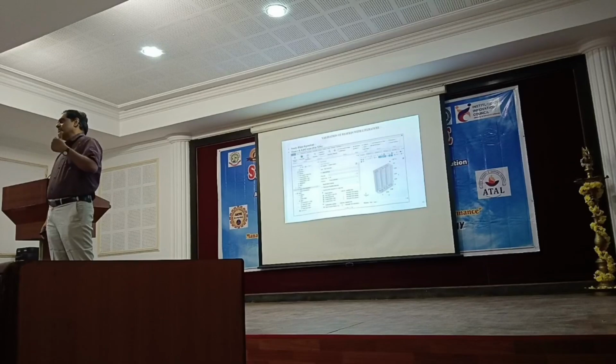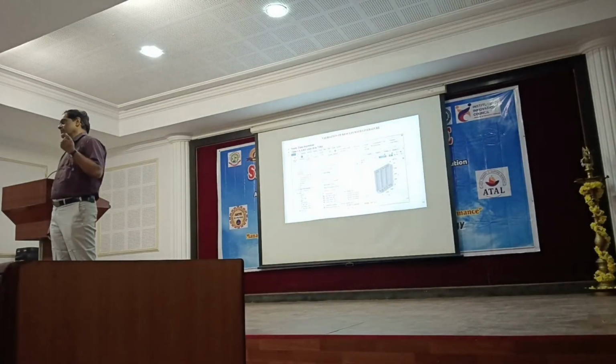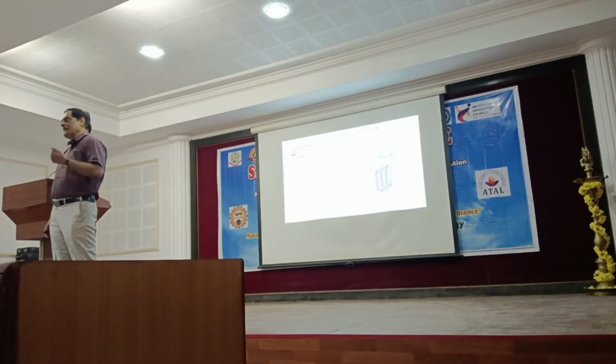Simulation is nothing but a virtual experiment. I already know how the system works. I try to represent it in the form of a mathematical model. In the mathematical model, I am connecting input to output. What do I need to input to get the output? For the given battery pack, let us say you are giving input as current. What is the output voltage I can get? And vice versa actually. Input and output are connected.